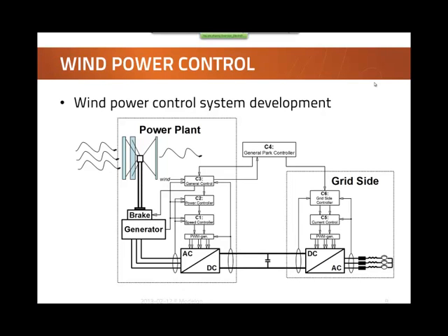A wind park has been basically modeled and simulated all the way from wind energy to the electrical generation by the generator, the conversion to DC link, and the inverter to take it back to AC with the grid compliancy. So this work was also including controllers, a number of local and overall controllers, for example to control the power and the tip speed ratio of the rotor.